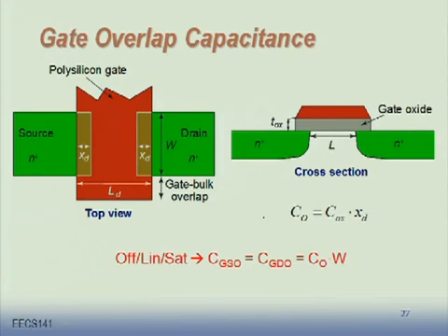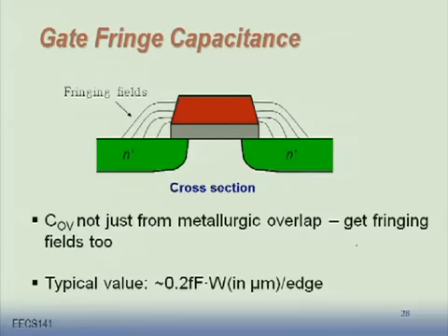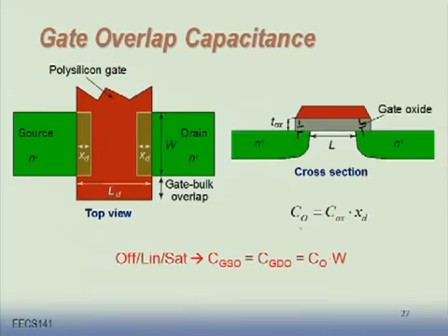And the capacitors, three-dimensionally looking, are here. So overall capacitance is equal to Cox times XD. And remember, this is capacitance per... sorry. If Cox is a capacitance per area, C overlap is per unit width. It's always given per unit width.